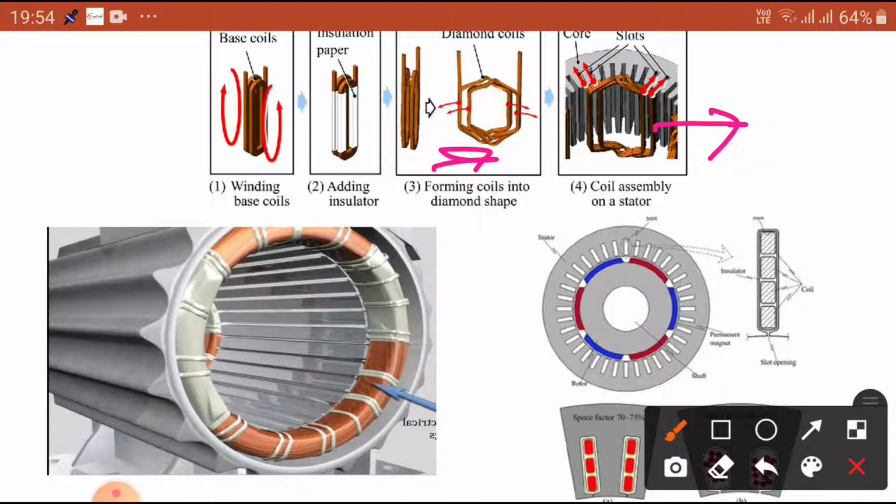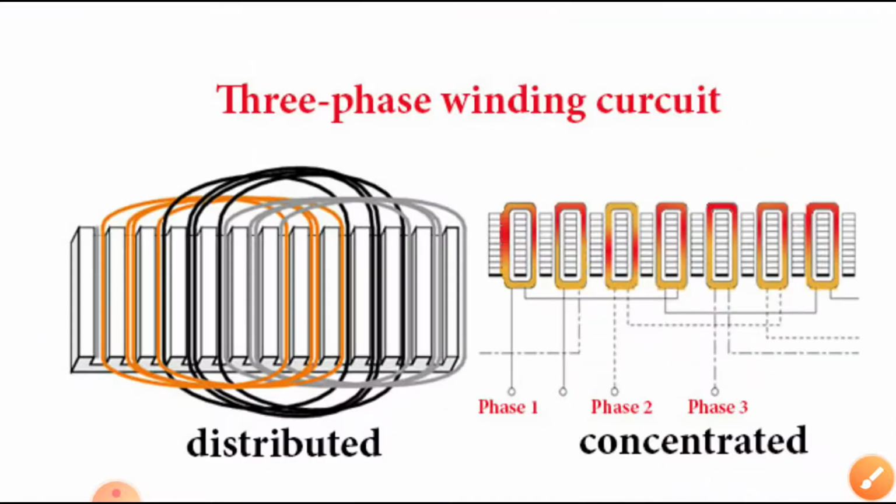Okay. So, how are these windings placed in the circuit? Already we have seen the AC windings may be of different types. We discussed previously mainly distributed windings and concentrated windings. In a distributed winding a rotating magnetic field is developed, whereas in a concentrated winding no rotating magnetic field is developed. For example, the concentrated winding is used for transformers, that is also one example. Okay. You can see here.